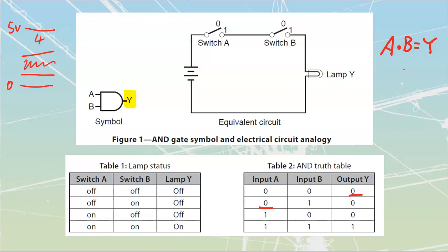This is Boolean algebra, and Boolean algebra is something you're going to learn about in 4th year. So we're going to leave it right now with just defining these, and then we can Booleanize those once we get into 4th year to combine stuff down there. There is a statement for this one that any low gives a low. As long as there's any low inside of here, we're always going to get a low output out of them.